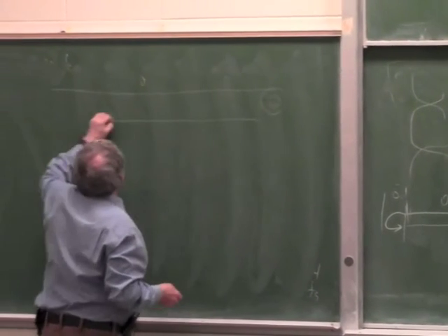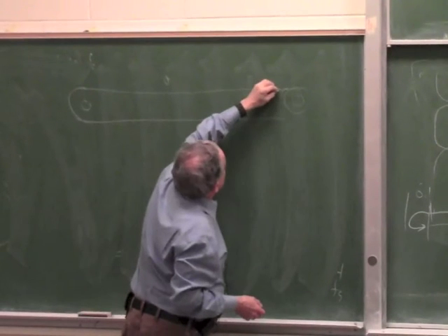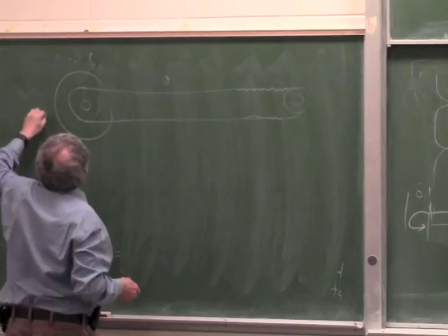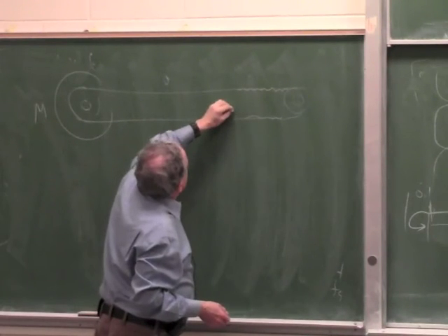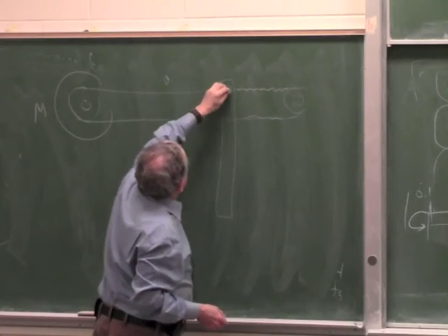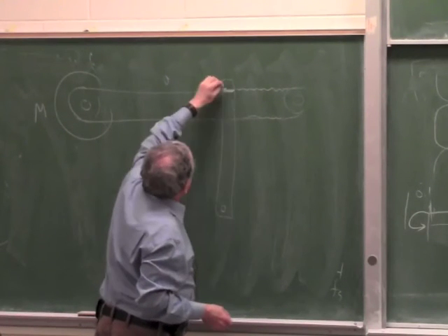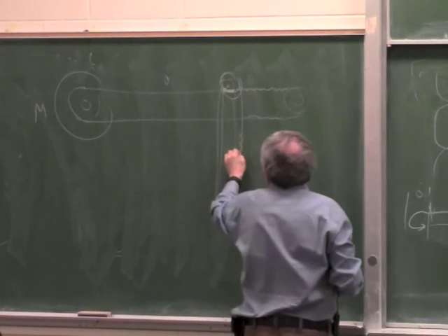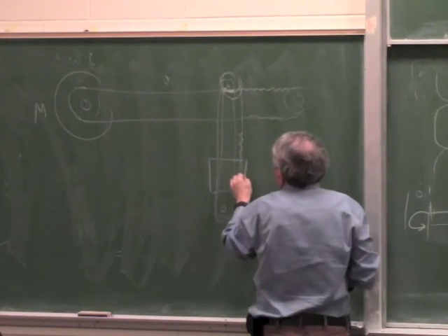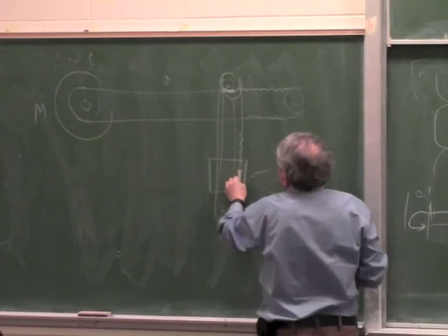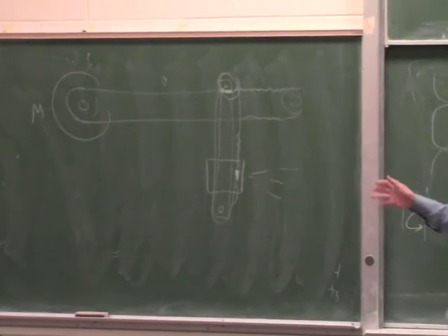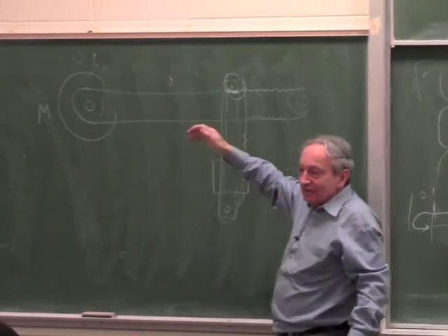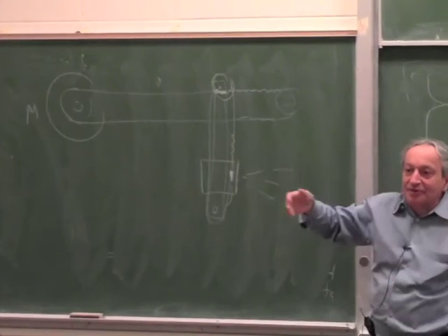So a good way to build it, you take a timing belt, connect it here to a motor, and then you attach the cross slide to the timing belt. And here you'll have the same. You'll take another timing belt with a motor, and then on this you'll have the spray gun attached to the timing belt. And this way you can do it with rotary motors. You don't have to make actuators which can move 5 meters. Okay? I mean, you can argue that you can use a linear motor, but it's much more expensive.